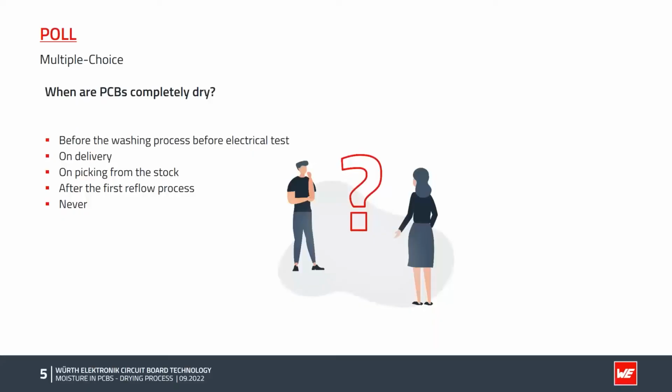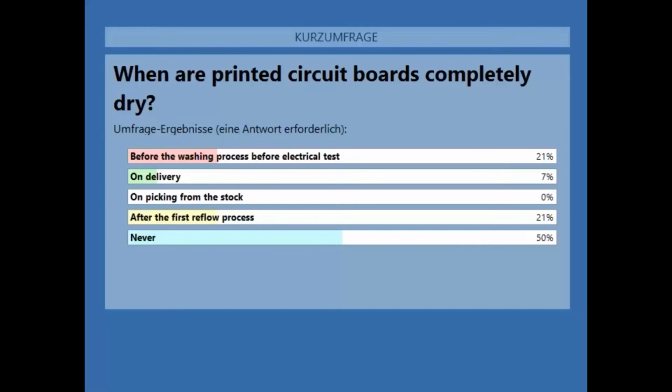Okay, so now we can see most of you, exactly 50%, have chosen never, and that's quite the right answer. So it depends how much moisture we have inside the PCB, but we can never say a PCB is completely dry in normal usage. Okay, so 21% have chosen after the first reflow process.